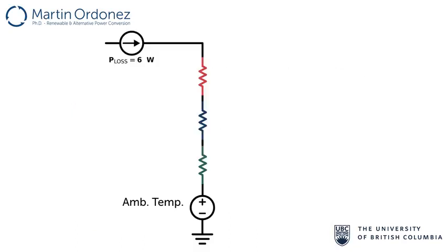Now, we can go back to our problem, which is the heat-sinked MOSFET. As calculated, we have the two thermal resistances, R theta SA, which is equal to 10.62 degrees Celsius per watt, and R theta CS, which is equal to 1.1 degrees Celsius per watt, since we have selected the silicon pad as our thermal conductor.